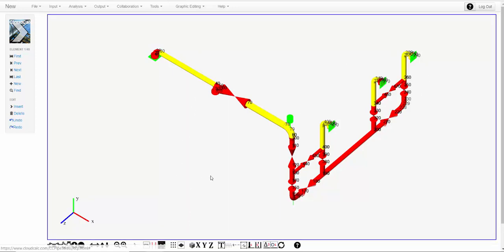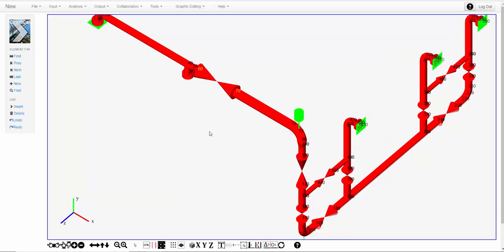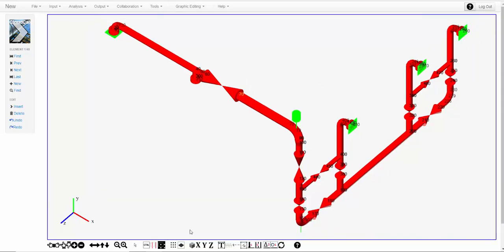This is select nodes, a nodal select. If you do that, grab the nodes you want to edit or work with. You may see it turns orange. Again, the control key lets you add to that. If you don't have a control key on, then it replaces the set. If we had a nodal grid that we set up, this turns on those nodes, whether they're part of the piping system or not. This is a little floor that is sometimes shown, which enhances or de-enhances your model.